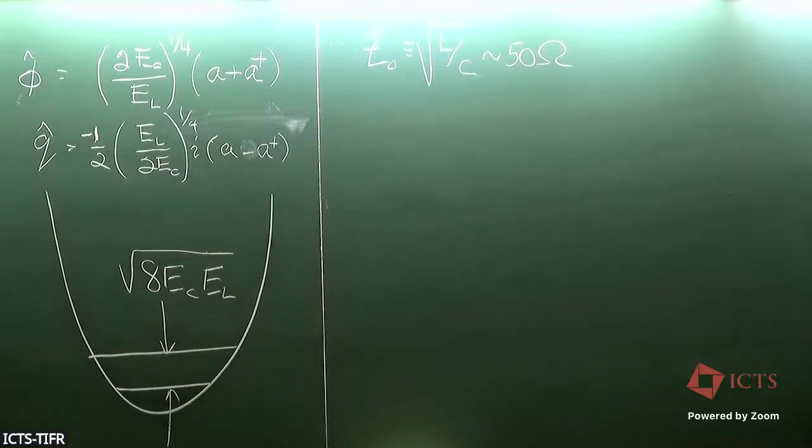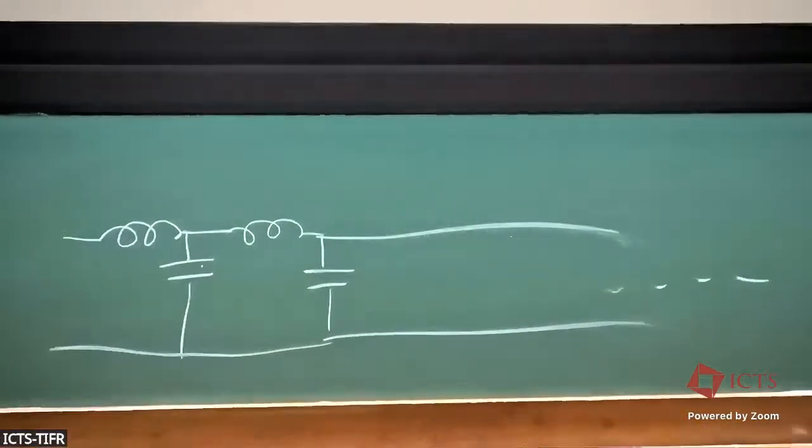Now, that's not really the end of the story. I can make a circuit, and I did in a previous lecture, where yes, you have 50 ohms and it's really, in a certain sense, dissipative, and that's the transmission line. A transmission line can be represented successfully with these circuit elements. You have a repeated ladder of inductors and capacitors, but it's important that it be infinitely many. So this is part of the idea that a resistor has very, very many degrees of freedom microscopically. That's an important principle of a resistor.